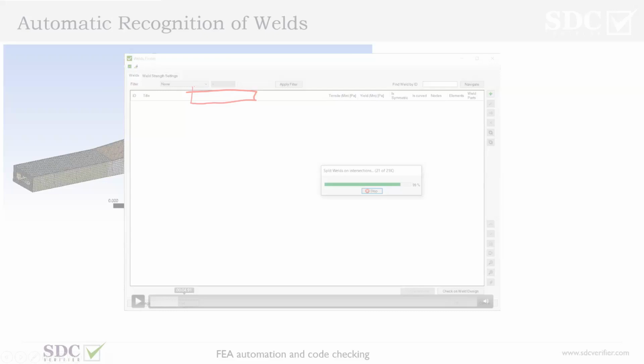But in general, we can still keep tracking this situation, because the general approach is that as soon as you get first results, you do a visual inspection based on them, and at that moment you're able to see whether your FEM model meets reality and whether your results match the real crane state.